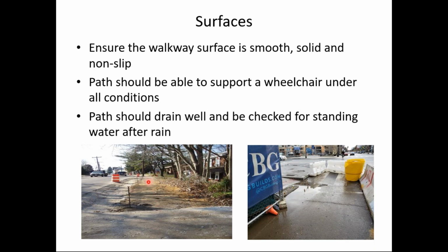Maybe on this day, looks like a dry winter day, maybe the ground's even frozen, maybe a wheelchair could go over that on that particular day, but it's not always going to be like that. You get rain or spring thaw, that's not going to be traversable by the wheelchair. So it needs to be traversable under all conditions. And make sure the path drains well and that you check for standing water and sediment and so forth after rains.